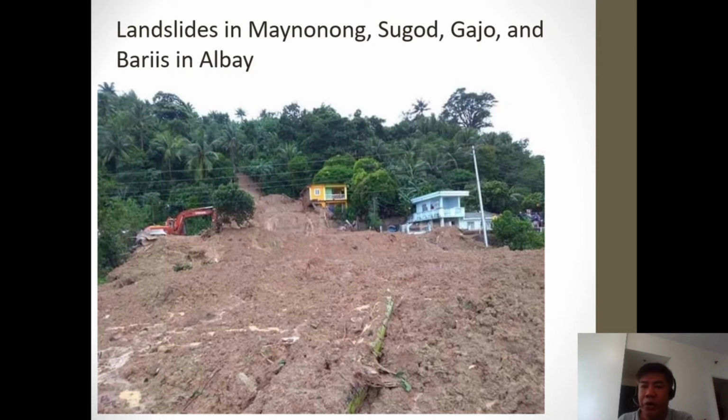The availability of boreholes, if there are any in the area, depends on the spacing, right? So you cannot have them spaced at very short distances because every borehole is very expensive, and it depends on the depth of the exploration. So that's one of the problems that those LGUs from the provinces encounter. Although if it is a big structure such as a multi-purpose dam, of course soil exploration will be included in the budget, so it is not that much of a problem.